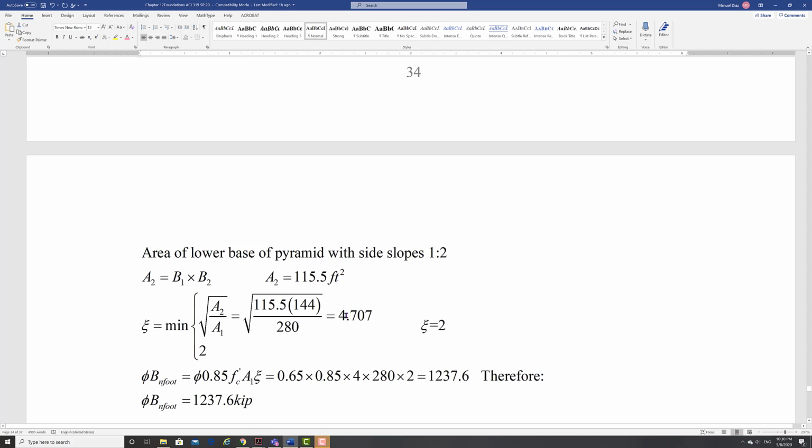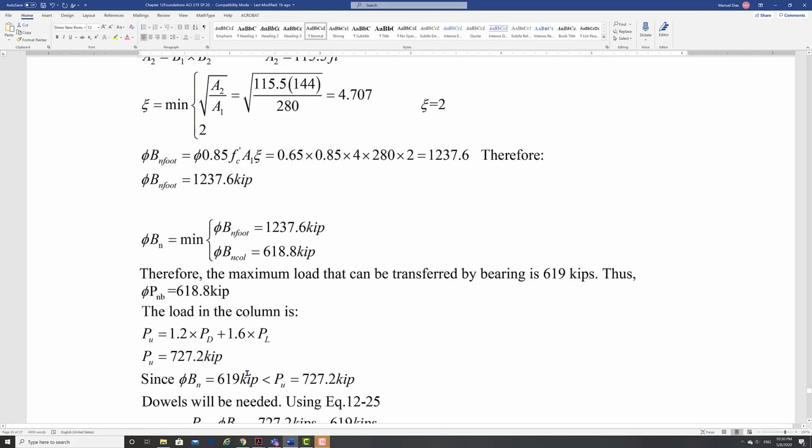Now this value is always pretty big. Okay, so 2 is going to control, and since this is the same as your footing, right? When you multiply by it, it's going to be the same as your column. This part right here is the same as your column. You multiply by 2, it's double already. So the footings rarely control, as I said, unless the strength is a lot bigger. Okay? So between the two values, you pick the smallest, and we change this one, right?